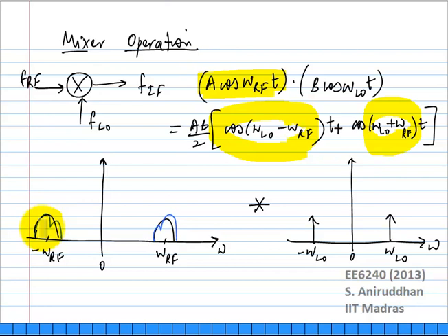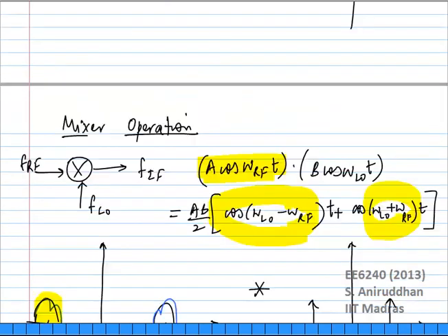Right? That seems very straightforward. Now, the problem is the input coming into your mixer may not be just a narrow band, because up ahead at the input you only have a band select filter. You don't have any other set of filtering. Okay, so whatever is there at the input will come in.